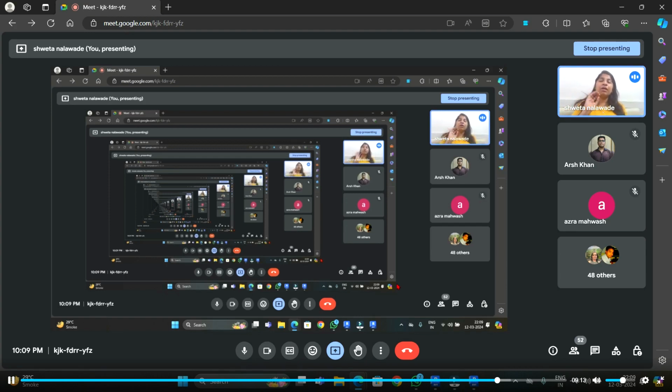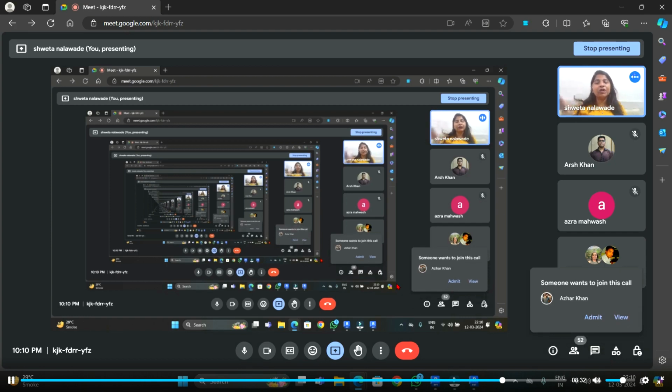Why? Because remember, in a BIM environment, your one file is linked to another. Your structure file is linked to the site file, but it happens vice versa as well: in your structure file, your site file is also linked. So when you're working in your structure file, you have a reference of the site file, and when you're working on the site file, you have a reference of your structure file. It's always interlinked, so whenever you want to extract data, you can extract from anywhere, but it depends what data extraction you're doing.